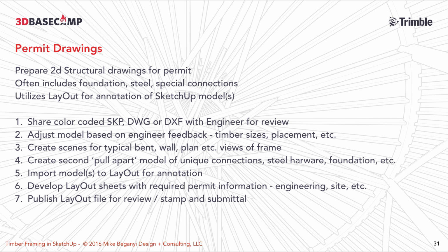So permit drawings are a little different than shop drawings, but permit drawings oftentimes have all this extra information. The building department wants to know what you calculated it on. What International Building Code standard did you use? What's the snow load that you use? Where's the building located? Is it an unprotected site or protected? There's all this stuff, and all that gets slapped into the drawing, and I'm using LayOut to do this.